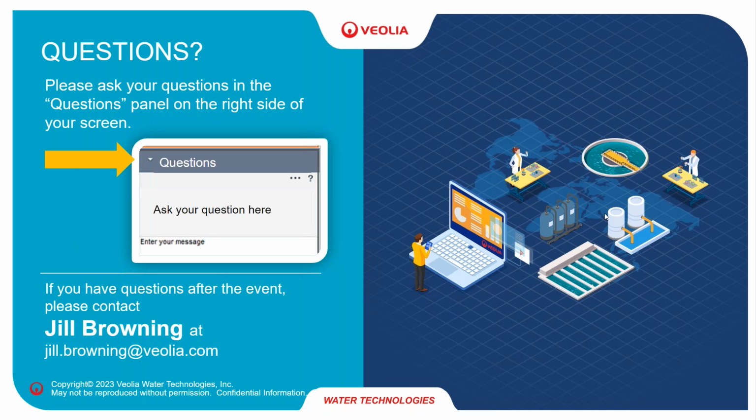So really, you need to look at your water analysis, the water chemistry, and what your temperature is. There's really what's achievable from a scaling resistance standpoint, and as I mentioned, CaptuRO adds its most value when you're talking about silica or calcium sulfate limiting the recovery. So, as I said, we could easily do about 15% higher in silica concentration than a conventional RO. And calcium sulfate, that's a little more tricky.